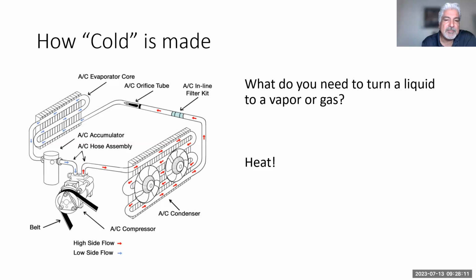But like I said, some of this metal we get is so fine. If you ever look at what happens on an orifice tube, the orifice tube's always been the telltale, and you can see that fine metal, and it'll still go through. So that's why those filters are better, in my opinion.